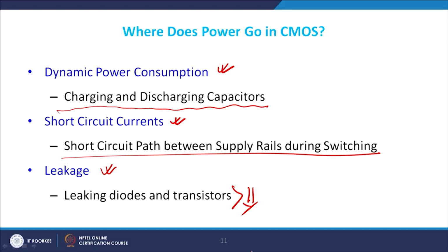So, these are some of the problem areas which you will face, the last two. The major contribution is that I will have a larger or smaller dynamic power dissipation, a larger or smaller short circuit power dissipation, and we also have a smaller leakage, which is basically a subthreshold leakage with us, right, and this is what we get from here.